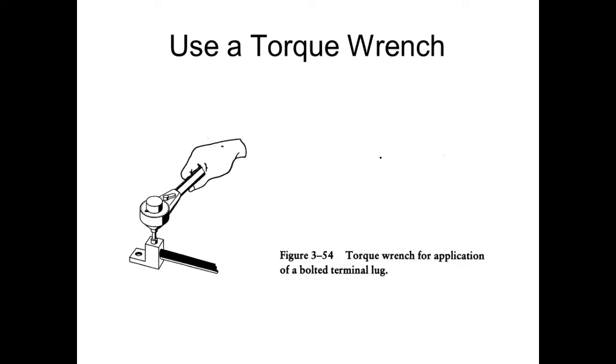We do have a torque. We do have, and I'll show y'all this too, one of the high voltage splices. When I show y'all the video, that's what you do. You don't have a torque wrench because the splice is not made to come off, because it's a high voltage splice. So what you do is you tighten it down until the head breaks off. And when it breaks, you know you got it to the right torque, which is pretty neat. And then you put a little compound in there. So you see that used sometimes on these splices that are not intended to be what? Taken off.